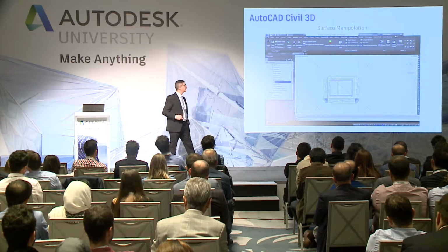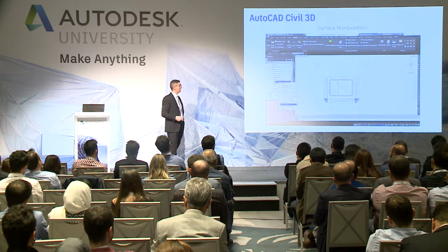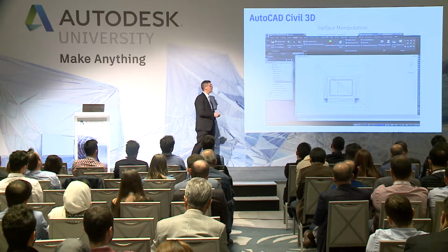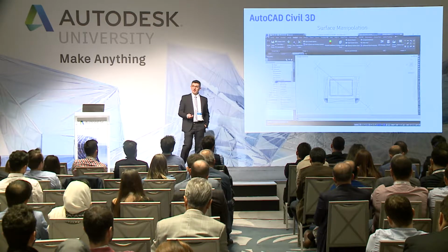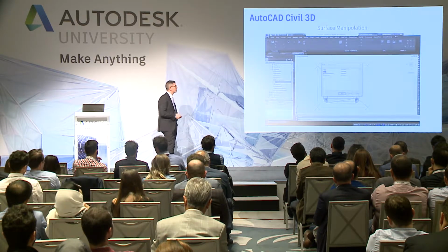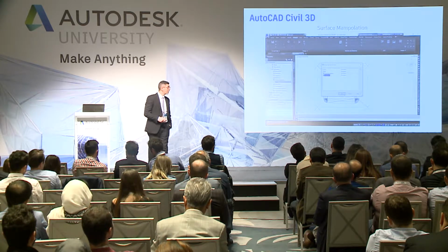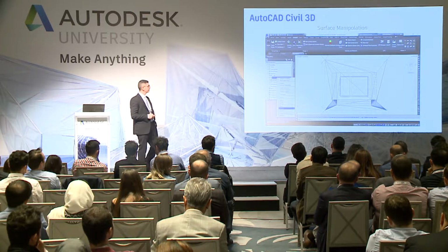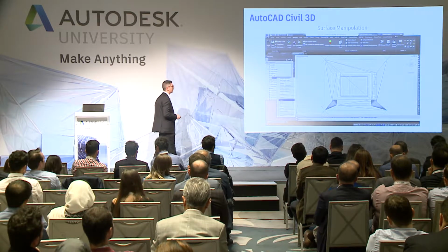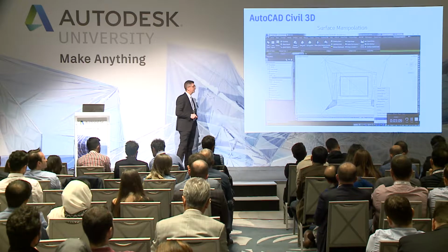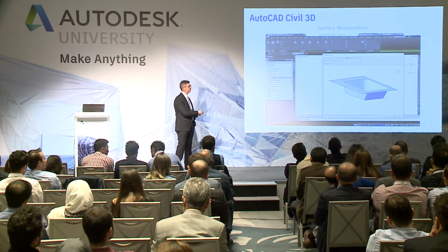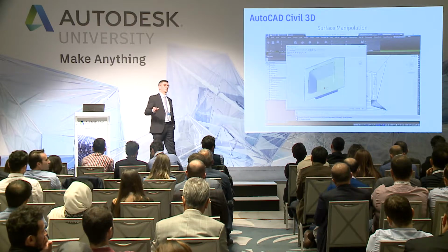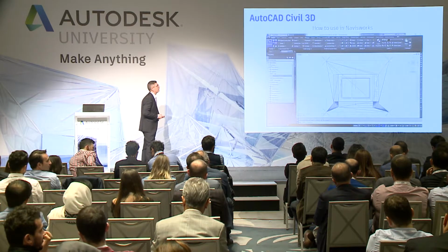You can find this type of operation like a paste, like in Windows. It's paste surface. Which surface do you want first? Existing ground. Do you want, again, the next one? It's paste surface, the volume. Click on OK. The new one is this. I can select it, and I can see it immediately in the viewer, like this one. This is the final surface. It's very easy, OK? It's paste surface and go in depth.